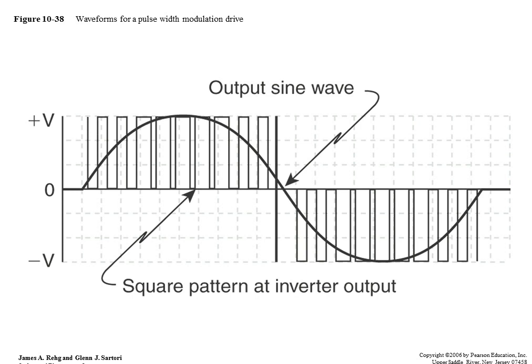That's exactly what your variable speed controller is doing. If you would take the variable speed controller, and we'll do that sometime, and hook it up to our oscilloscopes, you'll see nothing. Our oscilloscopes in the lab are too slow. But I have two 100 megahertz oscilloscopes, and they're storage scopes. You can store this pattern and actually see it. But the 20 megahertz scopes, which are normal for our lab, that I have a lot of, are just going to show an AC signal. You're not going to be able to see the other part of the signal.